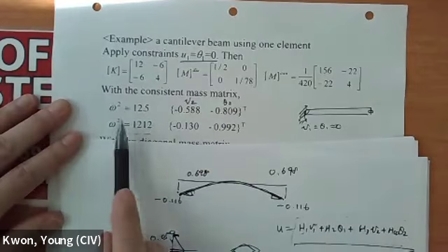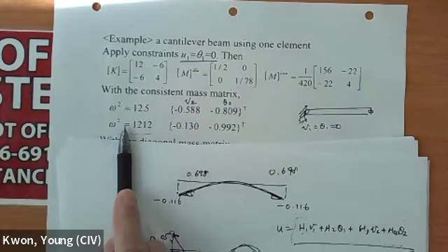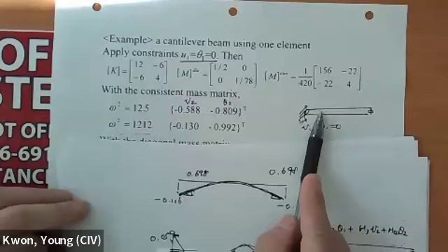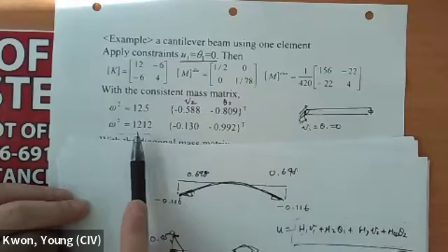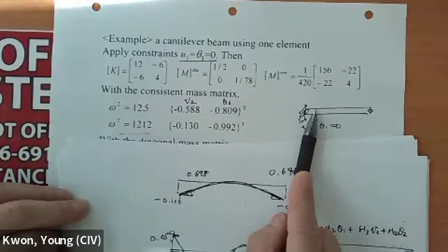So in this case, you don't have 0 eigenvalues, because you fully constrain any rigid body motion. If you have a 0 eigenvalue in here, then something is wrong in the formulation.